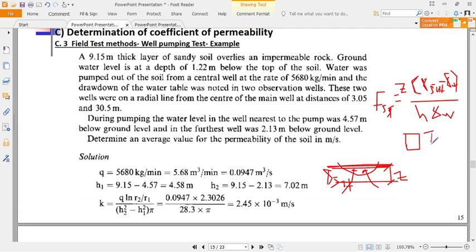So in the rainy season, the water is just at the surface. So we need to determine the amount of fill to put on this ground so that piping doesn't occur, so that the water is not pushed out due to the increase in water in the ground due to head H. And this head may be the rainfall which will be received, which will cause water to flow through this foundation. So how do you design that?